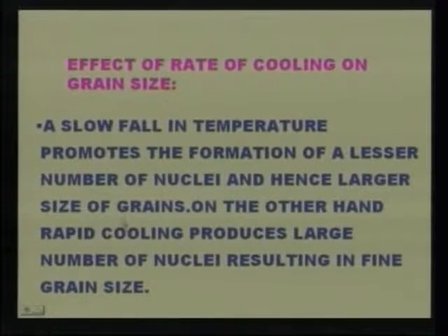As we have already discussed, slow cooling forms a lesser number of nuclei, therefore the size of the crystal increases, whereas rapid cooling restricts the growth of the grains, therefore it creates a larger number of crystals in smaller sizes, which provides fine grain size.